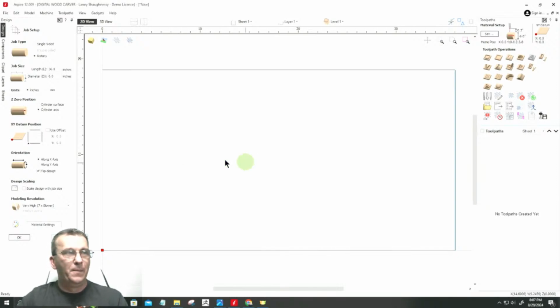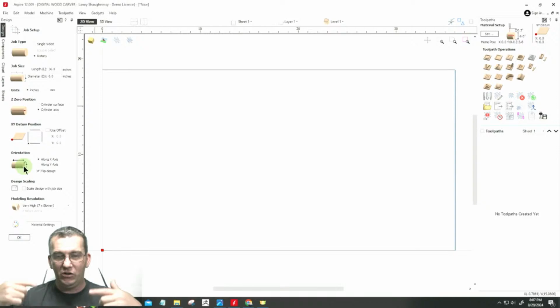For me, the length of my x-axis runs horizontally here on the screen. And so from top to bottom of the screen, imagine it kind of wrapping around my x-axis. But on other CNCs, depending on how your rotary axis is mounted, it could be running the length of the y-axis and the turning could be rotating around that y-axis, it being like your x or your a-axis.